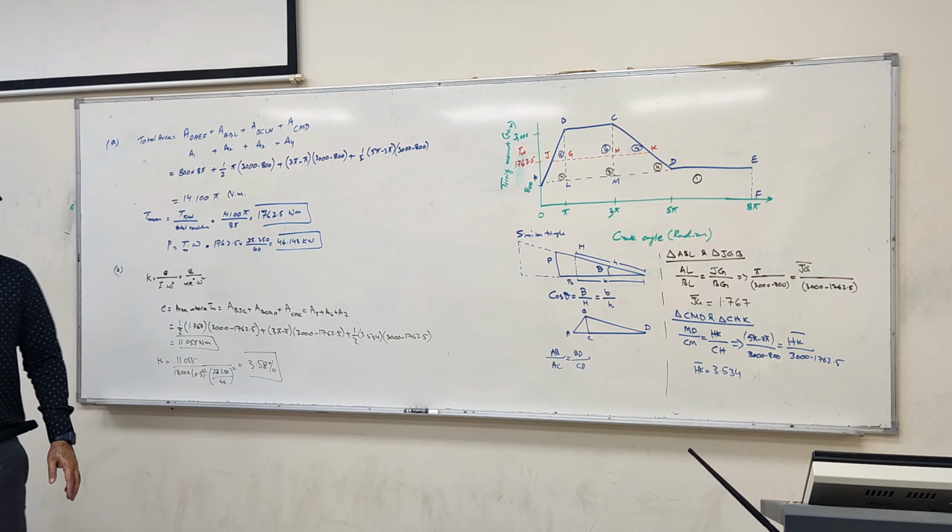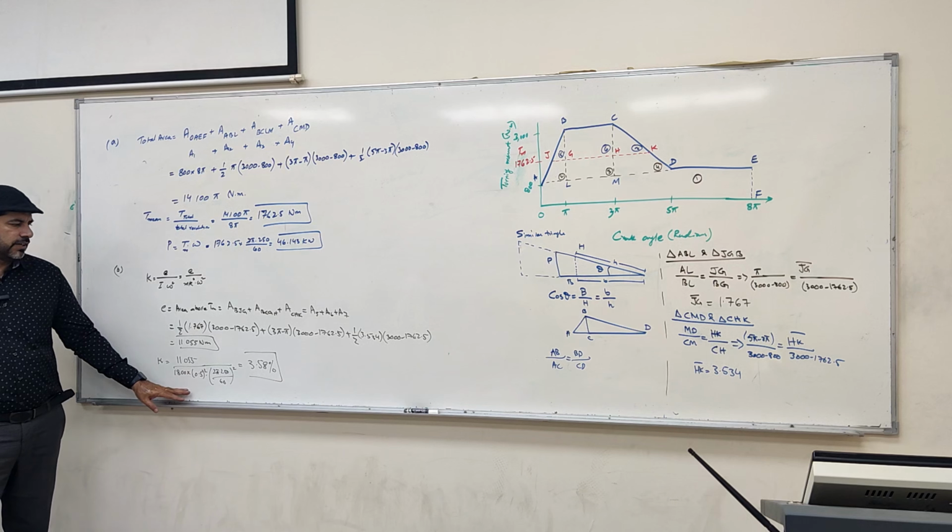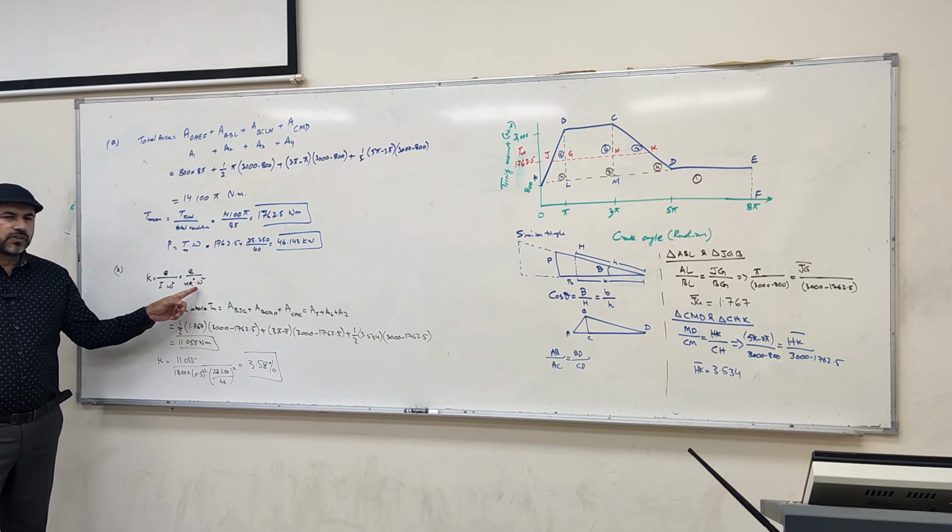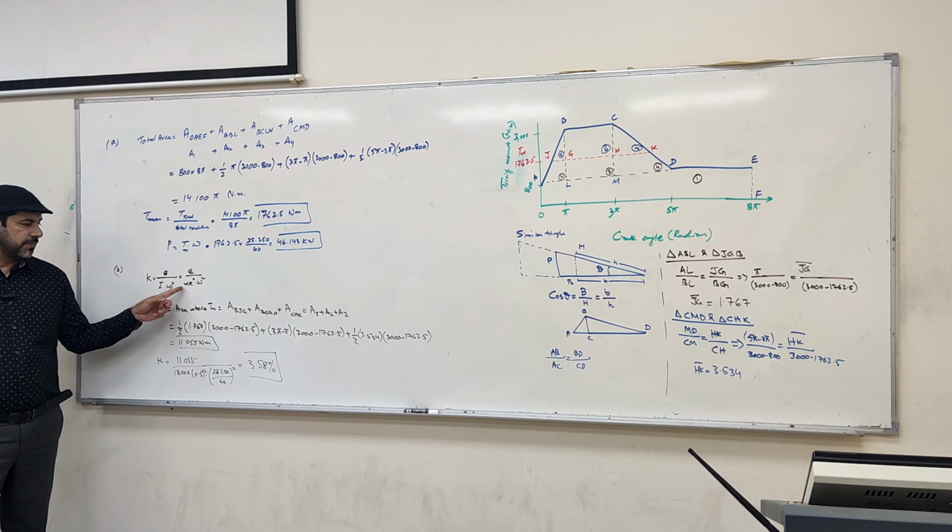Okay. If you want to reduce the fluctuation, what solution would you propose? Either go for the higher RPM, or mass, but the RPM and radius of gyration have a square effect rather than the mass. So better to increase the radius of gyration.